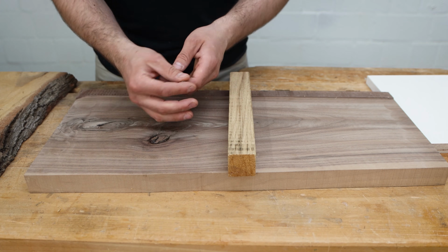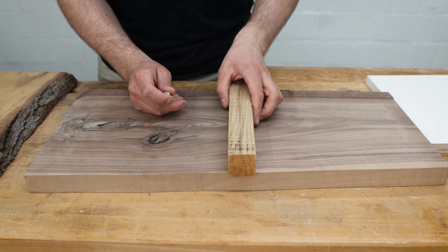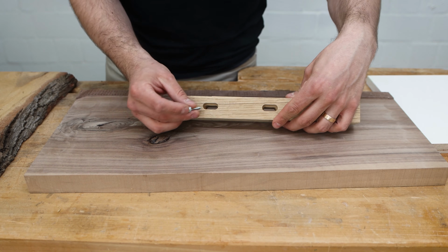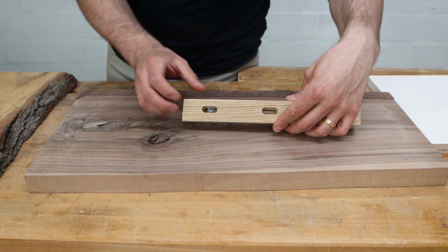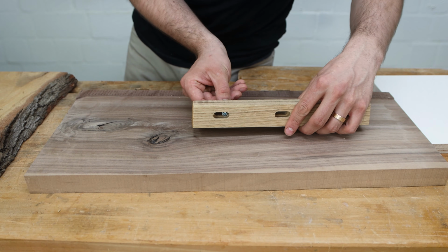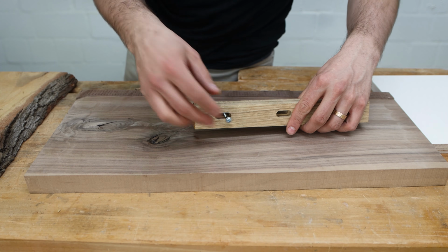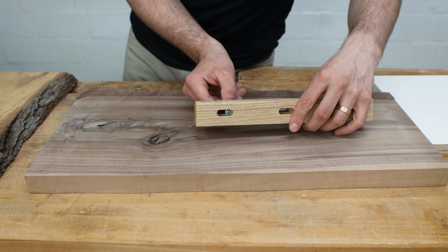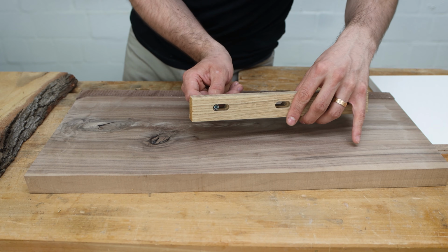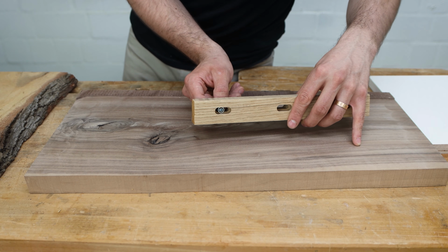To account for wood movement and hence still allow the top to expand and contract freely along this axis, but prevent it from warping or twisting, we can use oval holes. Just an oval hole where your screw goes in. It still holds the top to the base and it allows the wood to move freely in this slot. And of course, it's not smart to place the screw on one end of the slot. Place it in the center of the slot and you will be fine.